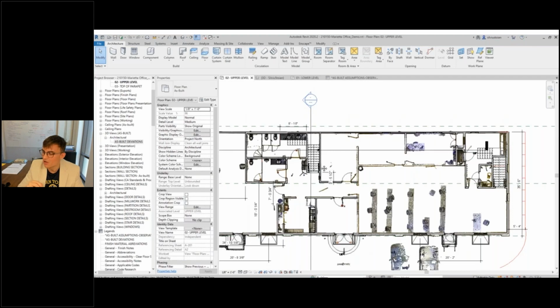When modeling, use all view types: plan view, elevation view, 3D view, view ranges, crop regions, things that will help you in interpreting the point cloud data. So if you captured in color, the point cloud will be easier to interpret. And if you captured 360 photos, you can do a side-by-side during that interpretation.